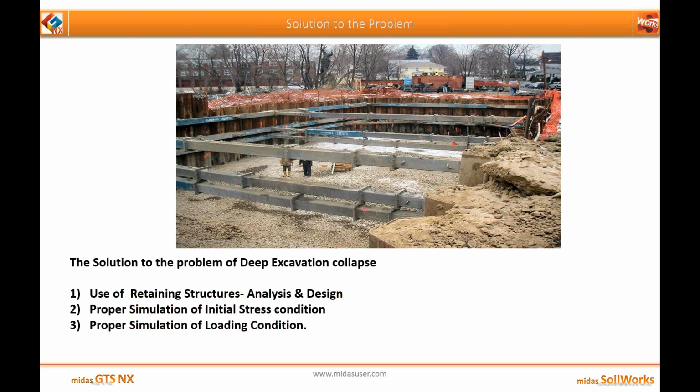Now, what is the solution to the problem? The solution to the problem of deep excavation collapses: first is use of retaining structure, their proper analysis and design, proper simulation of initial stress condition, and proper simulation of loading conditions.